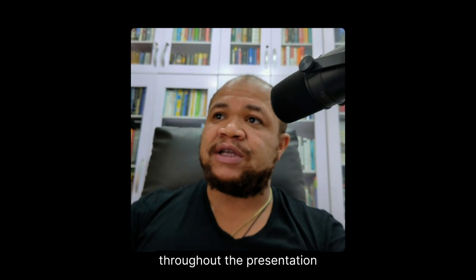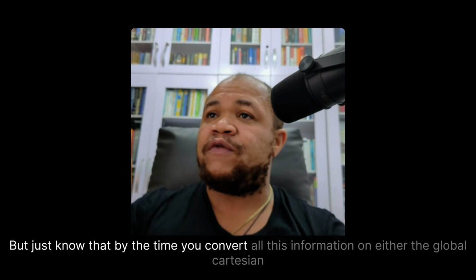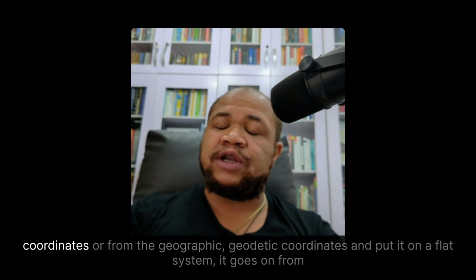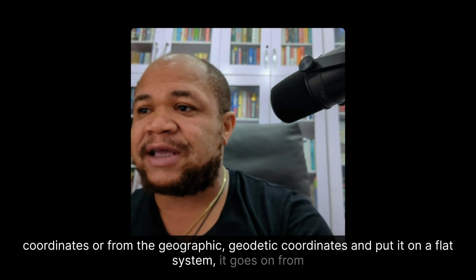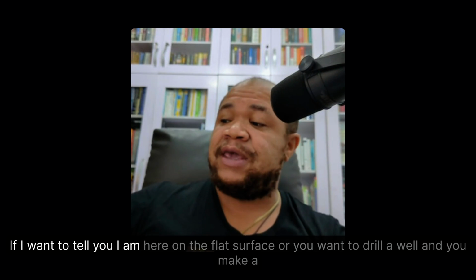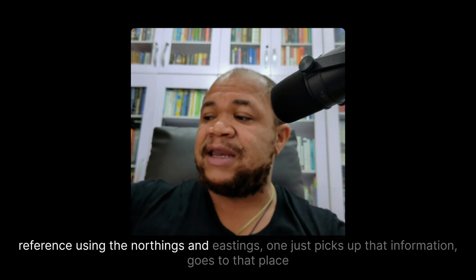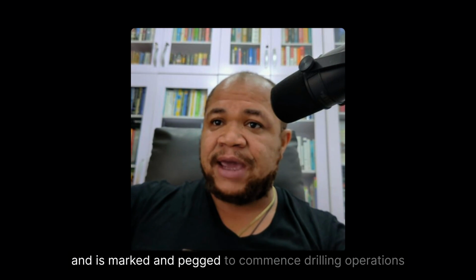It wasn't mentioned throughout the presentation. I just wanted to keep it simple, but just know that by the time you convert all this information from either the global Cartesian coordinates or from the geographic geodetic coordinates, and put it on the flat system, it goes from either longitude and latitude to become your northings and eastings on the flat surface. So if I want to tell you I am here on the flat surface, or you want to drill a well, and you make a reference using the northings and eastings, one just picks up that information, goes to that place, and it is marked and pegged to commence drilling operations.